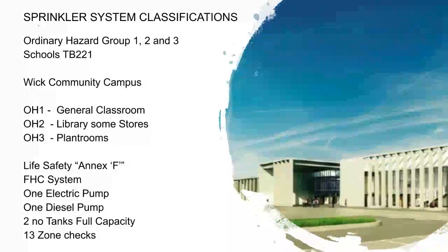Okay, now schools. If you go to the technical buildings for schools, DB 221, it will generally say that schools are protected to Ordinary Hazard Group 1. But there's also a recommendation in there that a fire risk assessment should be done. So what they tend to say is that smaller schools are Ordinary Hazard Group 1, but when you get into larger schools, you'll need to start looking at putting up to Ordinary Hazard Group 3.